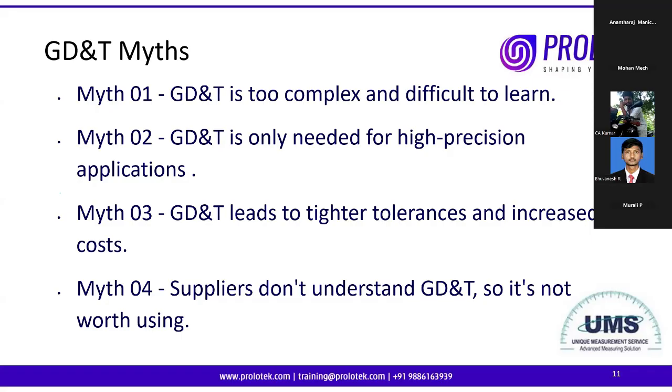Another advantage of using positional tolerance is that it is a feature of size control, we call it. As I told, concentricity and symmetricity are feature controls. Position is a feature of size control, which means, as Josh was explaining in one of the classes, the maximum material condition modifier can be used to get bonus tolerance. With concentricity and symmetricity, we cannot use the maximum material condition modifier according to the ASME standard. That is allowed only with position. Many people started using position, and concentricity and symmetricity had very little importance. So the ASME committee took a decision to delete those two symbols.